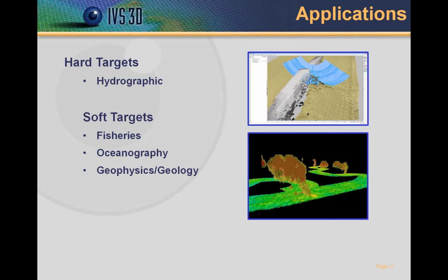So for example, when you do a multi-beam survey of a wreck, that wreck could have masts or cables or nets that have been snagged over the wreck that show up really well in water column but don't necessarily show up in the multi-beam solution. So folks are integrating data from the water column with their traditional multi-beam survey to get a better representation of what the wreck looks like on the seabed.